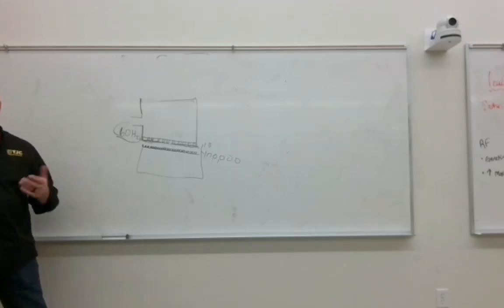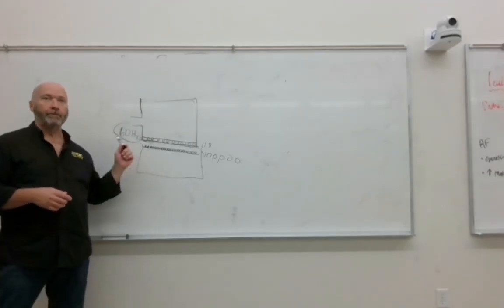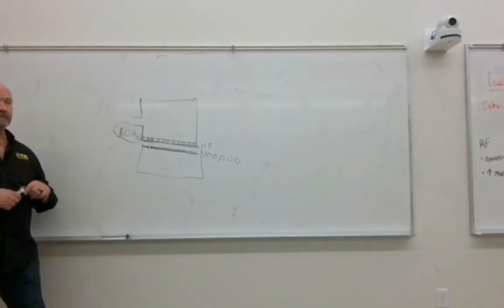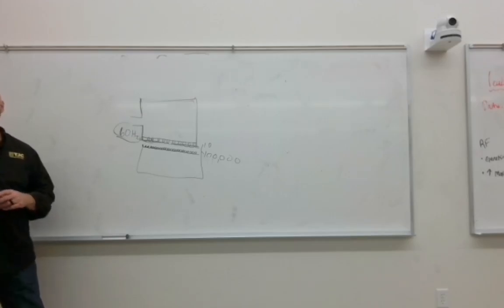So that turns ratio doesn't need to be drastic, but in the high voltage transformer, what I'm taking is voltage from 220, 240, let's say. I'm trying to boost it up to maybe 110,000. So it's got to be big. Our turns ratio may be as dramatic as 1 to 30 to 50,000. It's going to be big.